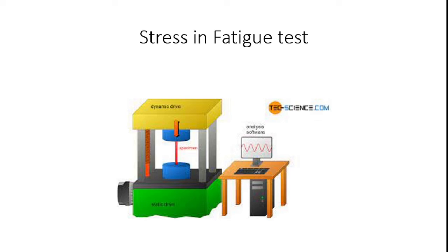Here in the plot you see hills and valleys. The mean stress is midway between the extremes. If I draw the mean line, the midway can be found from this. The stress midway between extremes is called the mean stress. The stress range means the variation between the extremes.